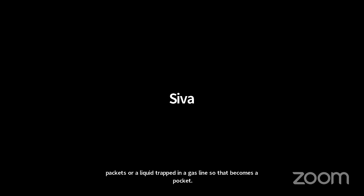Okay. Next question. What are pockets in a pipe? Pockets are nothing but a mixture of fluids. You have gas trapped in that liquid line, or a liquid trapped in a gas line. So that becomes a pocket there. In that flow, there is a pocket of liquid and a pocket of gas. That's it. It may create two-phase flow, and that may damage the pipeline if not designed for that.